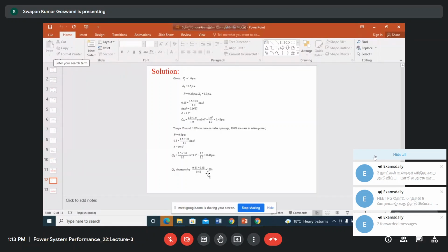So we have previously discussed regarding system that active power and delta, they are strongly coupled. Reactive power and delta, they are weakly coupled. You see that here delta is increased, and as delta is increased, active power is increasing. Very large increase in active power, 100%. But what is the reduction in reactive power? Only 15%. So here also the same fact is established again that delta and reactive power, they are very weakly coupled. And delta and active power, the coupling is strong.